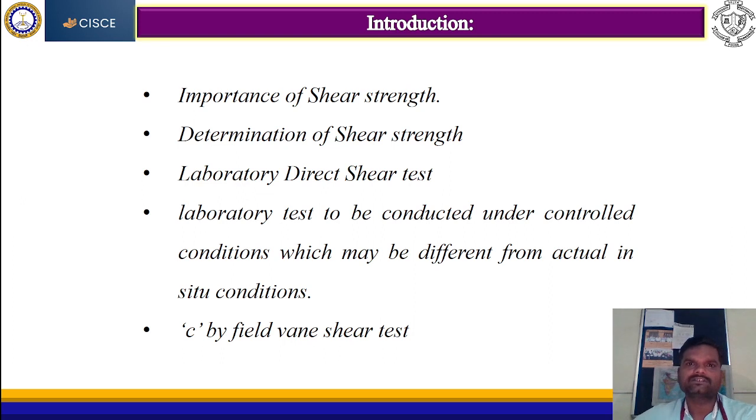But the laboratory direct shear test method is very useful, and it is very simple to perform for sandy soil or sand particles. But we know that it is conducted under controlled conditions, which may differ from the actual site condition. That's why we think we should go for field testing.